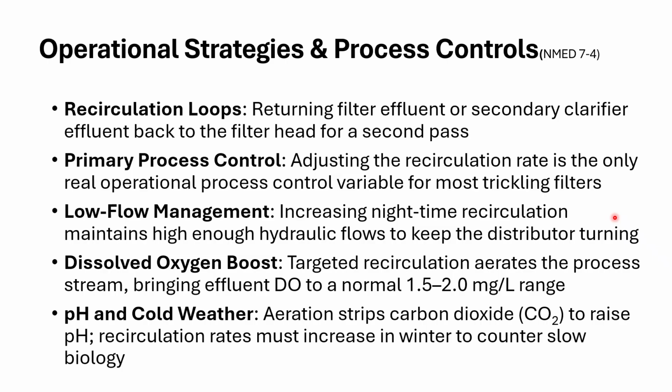Then a couple of hours later, the peak starts hitting the wastewater plant. Then it dies out. And then we see another peak, not as big, as people start getting off work and they go home, they cook dinner, they wash clothes, they do whatever they have to do. And then around 7, 8 o'clock at night, we see a second peak because it takes a couple hours for that wastewater to hit the plant.